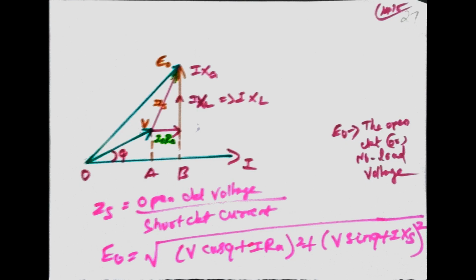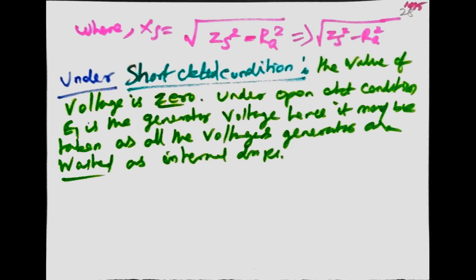That is the synchronous impedance method. The graph is drawn from the OCC curve and SCC curve. From this graph, we obtain E1 and IF, and ISC and I1 values. From these values, we obtain the regulation value.